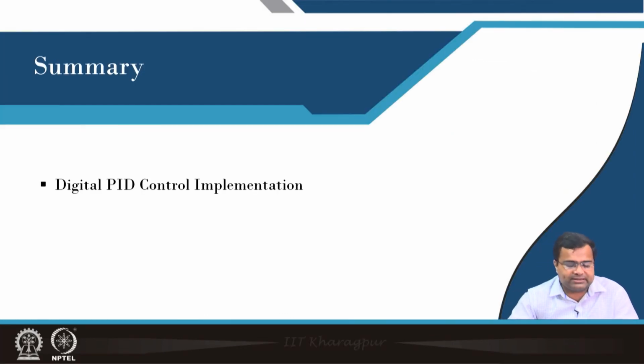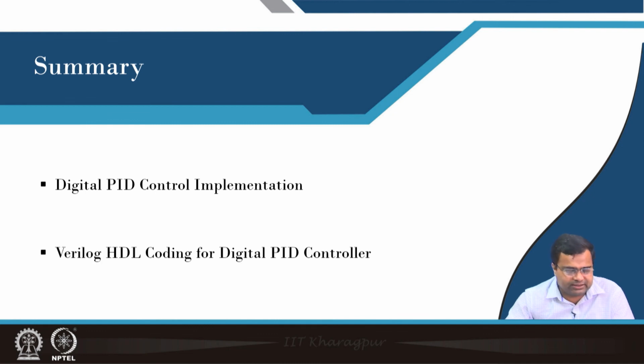So, in summary, we have discussed digital PID control implementation, and we have also discussed Verilog HDL coding for digital PID control implementation. We will discuss the live demonstration of this PID controller, the transient response, in the subsequent lecture, and that is it for today. Thank you very much.